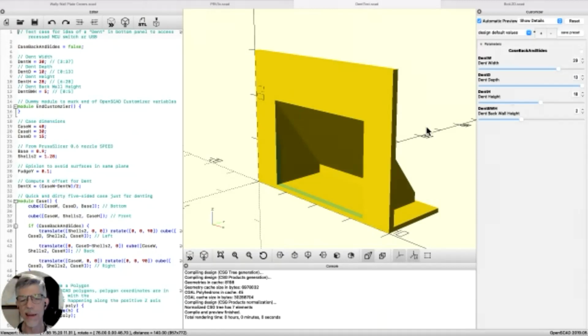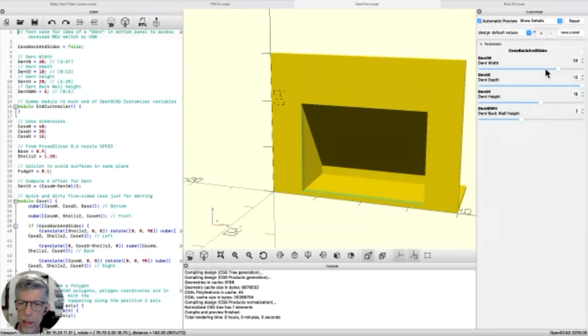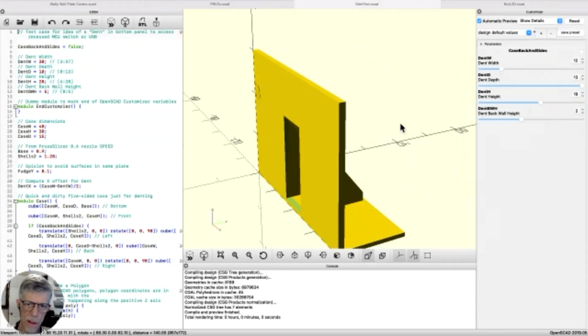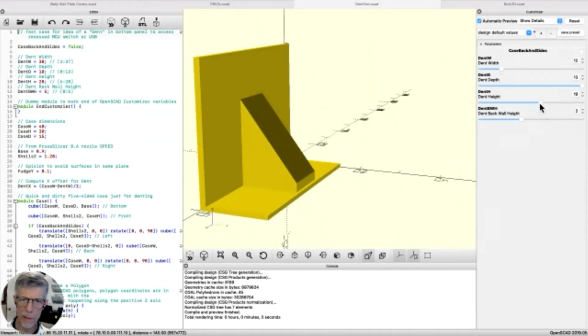Yeah, I glossed over that. So it's essentially I'm eyeballing it, but I don't have anything in the model. I could, but for instance, if I make this width small enough, right? So I make it very small, then I probably have the ability to bring the height down and go to a much steeper angle, right? Because now you're not stretching the filament over as wide a distance, right? Right. And okay.